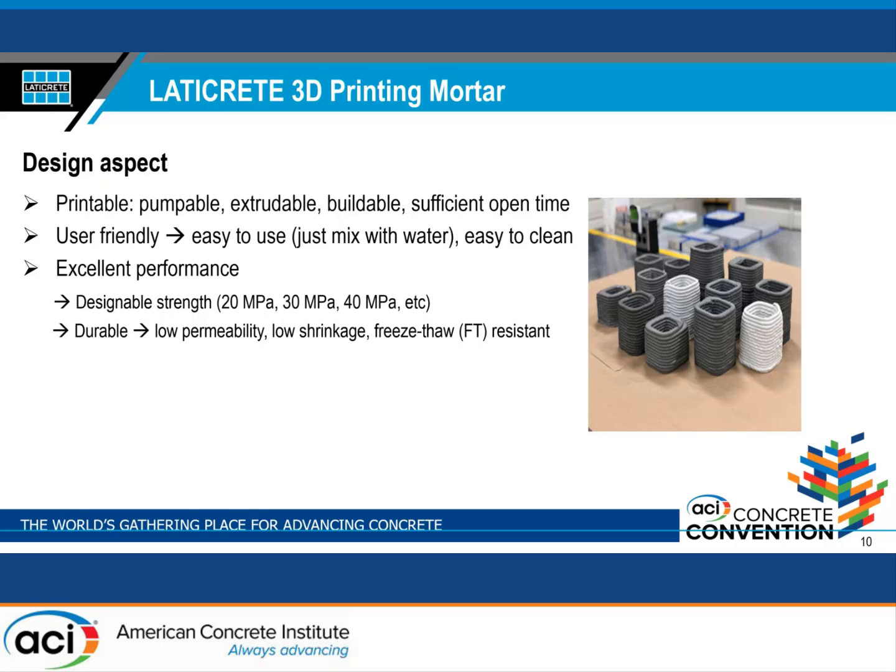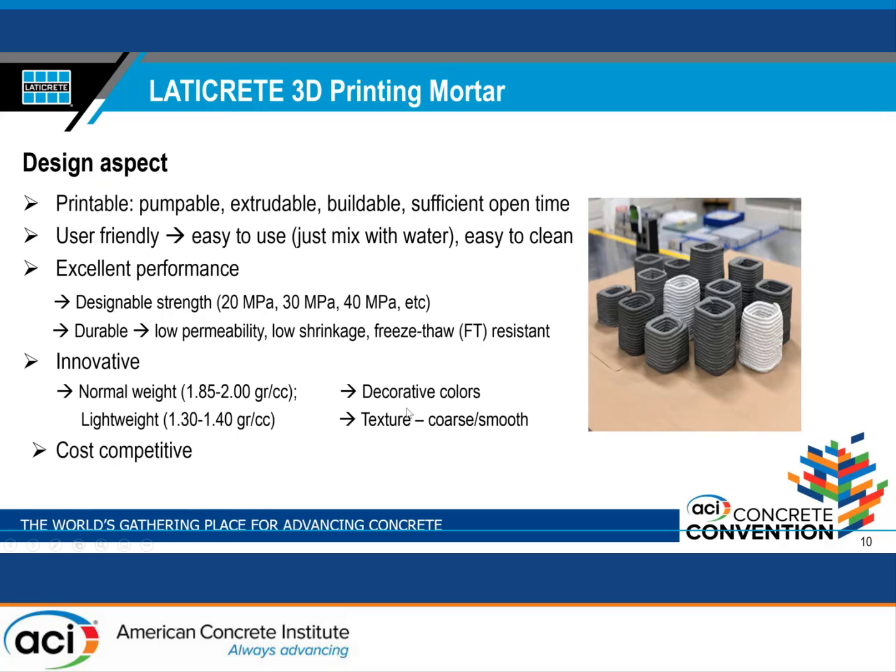We pass the freeze-thaw test ASTM C666, with a durability factor above 95% after 300 freeze-thaw cycles. Our design is also innovative, in which we can design with different weights, colors, and textures. And of course, our products are cost competitive while maintaining their quality.